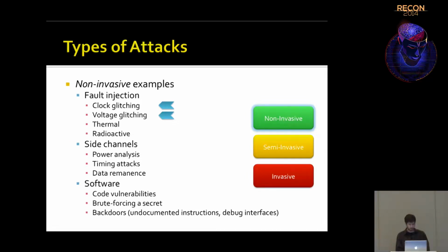Timing attacks: you're watching the response time of maybe control flow in a loop. If it goes to this condition, then it takes this long; else, if it's doing some other operation, it's going to take even longer or shorter. So it gives you some cues what operation the device is doing. Data remnants, that is kind of like your cold boot attacks.